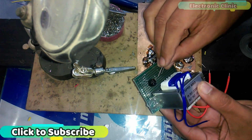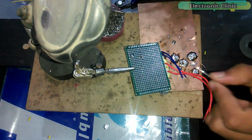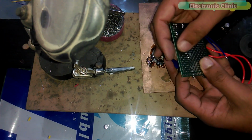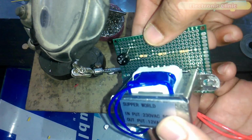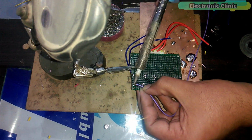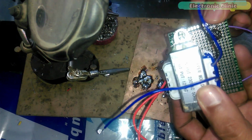Now connect 2 more resistors in series. Now connect the last resistor with the ground leg of the bridge rectifier. Now connect the secondary wires of the step-down transformer with the AC legs of the bridge rectifier.